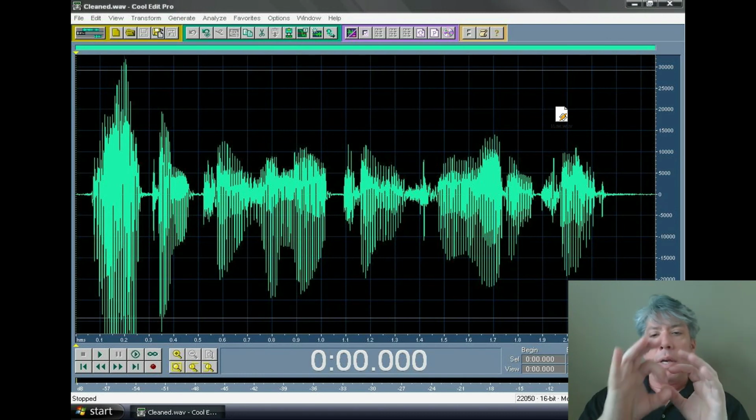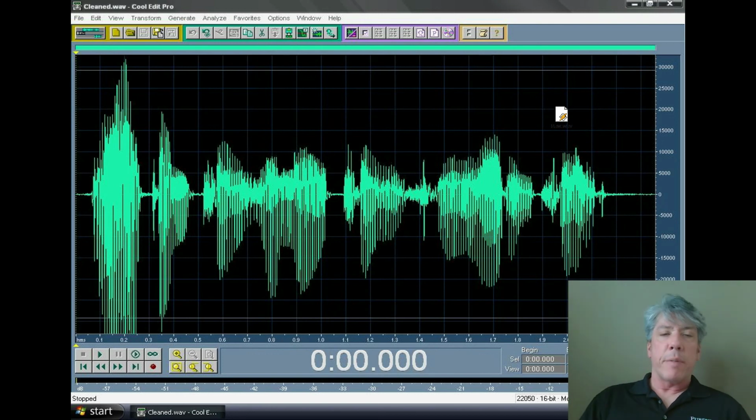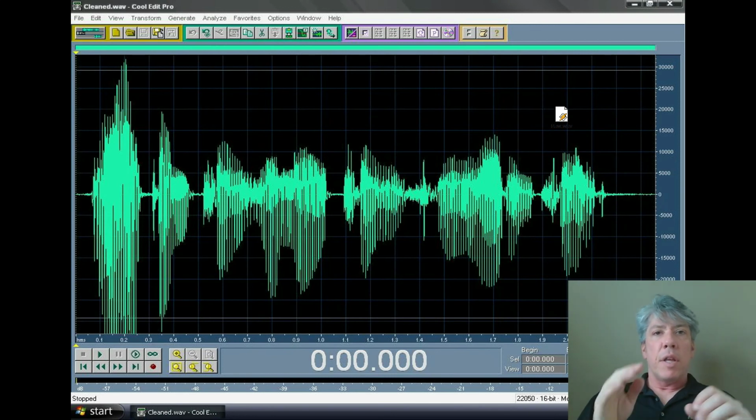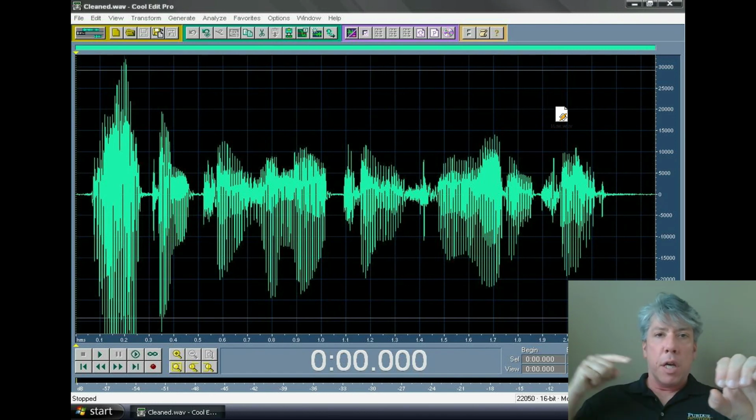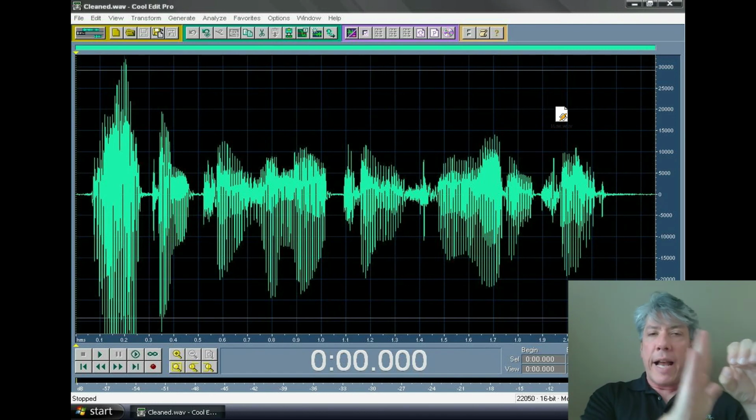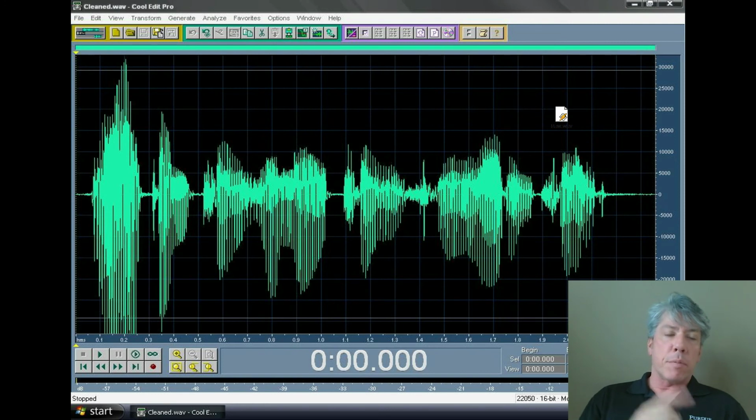The way it works, it's basically got a little round diaphragm. It looks like it's made out of shrink wrap or cellophane, basically a thin diaphragm, and when you talk, if you're touching it, you can feel it actually vibrate. It has such low mass that the variation in air pressure from your voice will make it vibrate. So all you do is mount a coil of wire on the back of it, just very fine magnet wire. Put it into a magnetic field, and as that diaphragm moves, it will generate a voltage signal.